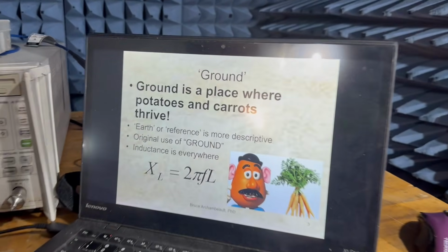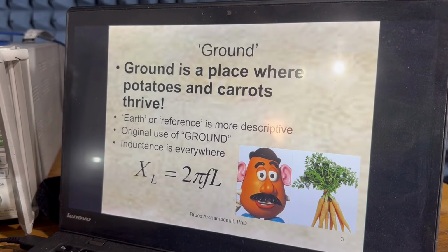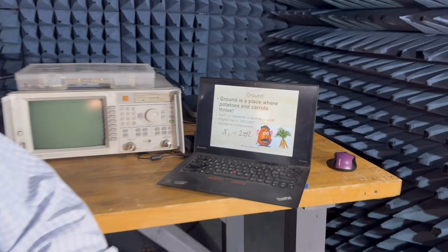Well, one of my favorite phrases is ground is a place for potatoes and carrots. The idea of using earth or reference is actually more relative and more accurate. I think that we'll talk about the original use of ground, but the bottom line is the inductance associated with the connection to the ground, whatever that ground is, is going to make the ground connection not as good as it should be.